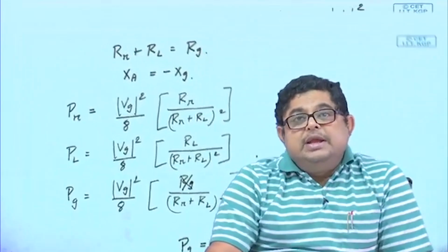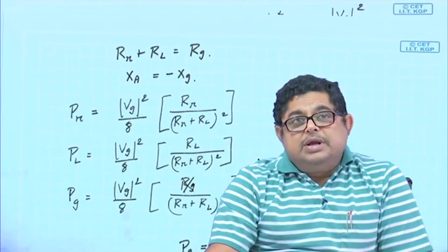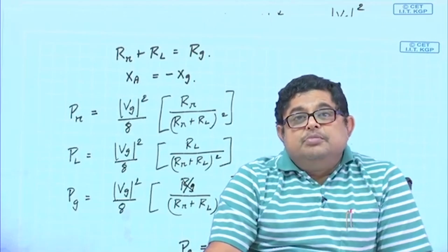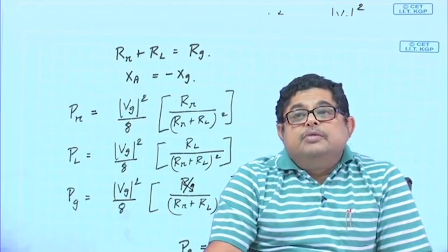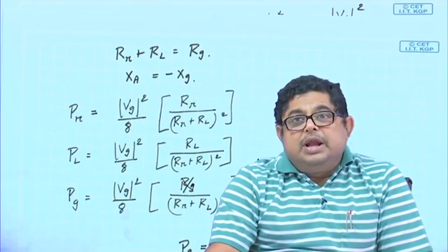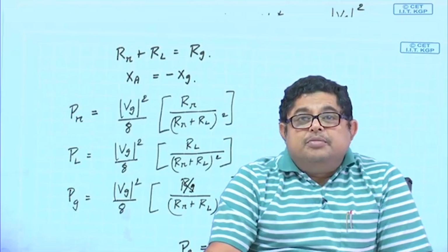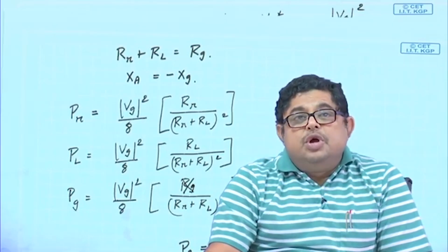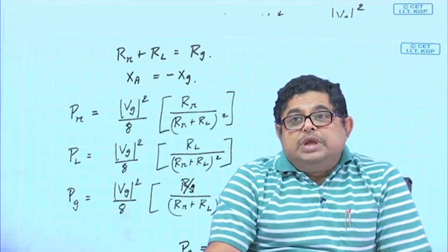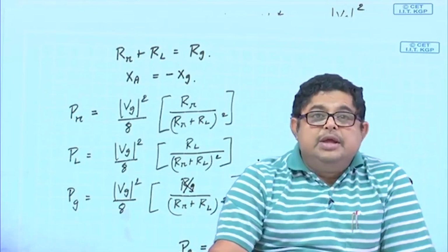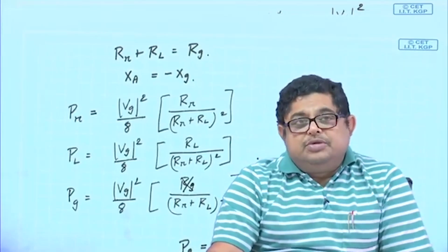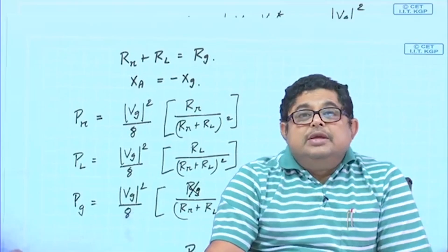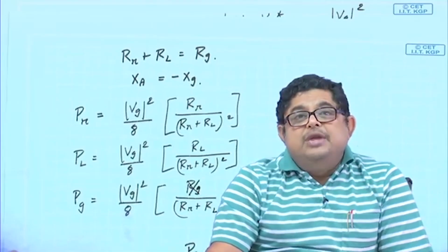That is why for any antenna we generally try to find what the impedance is, and we have seen that people generally demand, for modern antennas nowadays, that the reflection loss should not be more than 10 dB. That means 1/10 of the power can be allowed to be lost. So, the 10 dB impedance bandwidth is a useful parameter for an antenna.